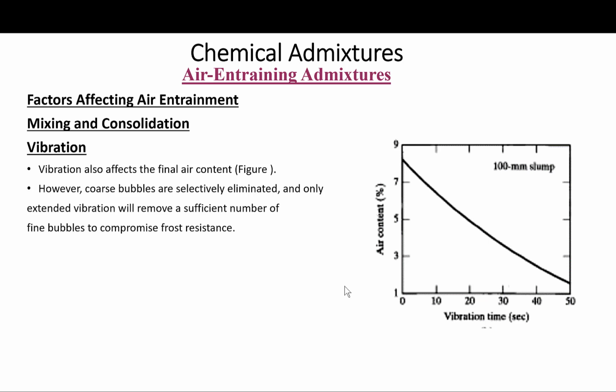So let's see the effect of the vibration. And again, while placing the concrete and doing the consolidation and the vibration, that also affects air entrainment. Vibration will affect the air content, as can be seen from this figure. As vibration time increases, air content goes down.